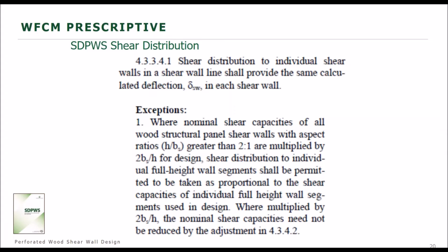In the 2018 update, it applies to both wind and seismic. So you'll see us use this adjustment later, but in the 2015 version, it does not apply to wind designs. It only applies to seismic designs. When you get into the special design provisions for wind and seismic, it's applied to both wind and seismic designs.